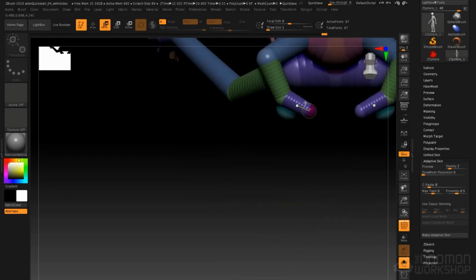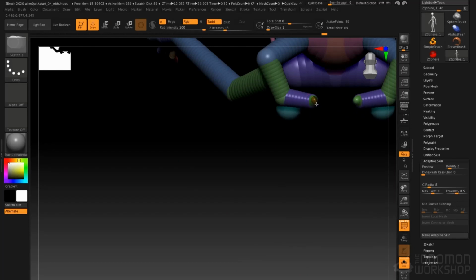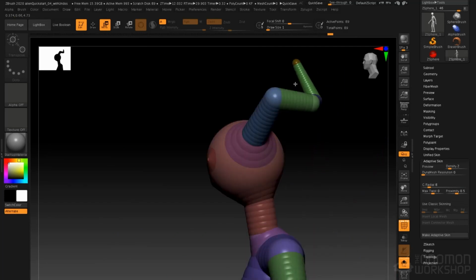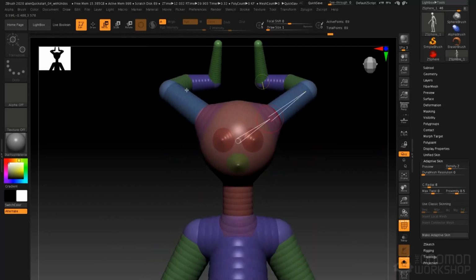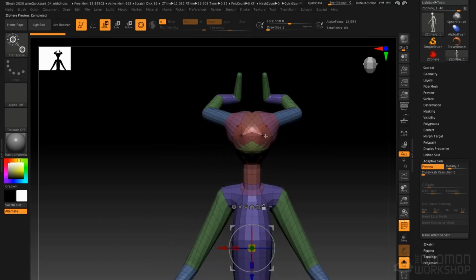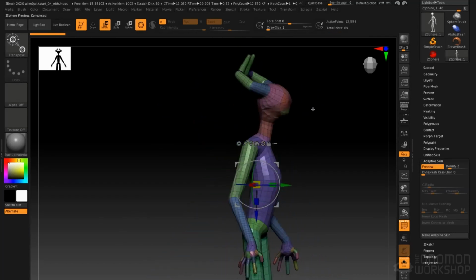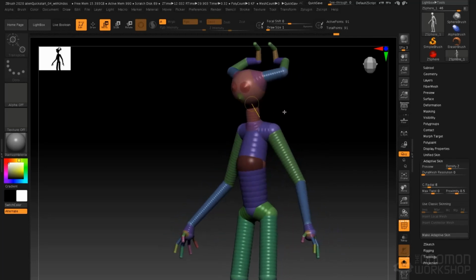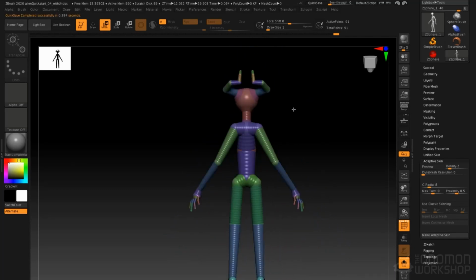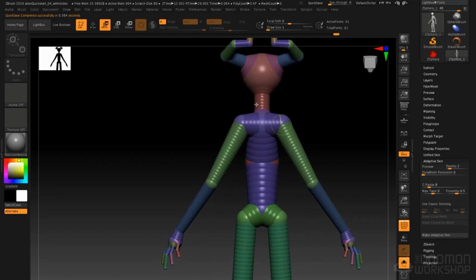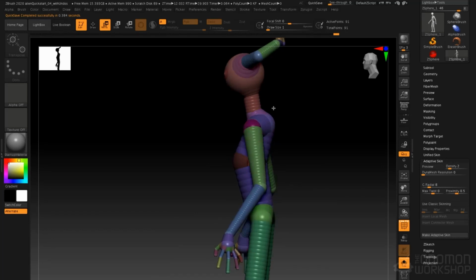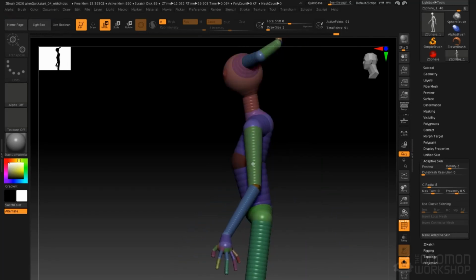And that way I can start to adjust the curve of these horns. We can get kind of an interesting effect here. Let's go ahead and draw a child sphere here. For the very, very tip of the horn, let's move that up and forward. Press the A key, and there you can see our preview mesh. I'm going to add one more child in between these last two, just give it a little bit more curvature. And there we go. Now let's say that at this point we decide we need wings on here. So what I'll do is I'll take my shoulders, let's move them forward just a little bit to give ourselves a little bit more room to place wings here.